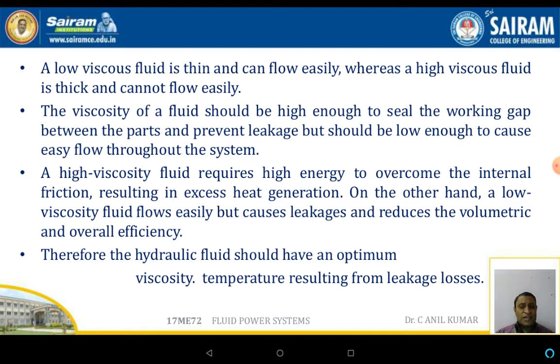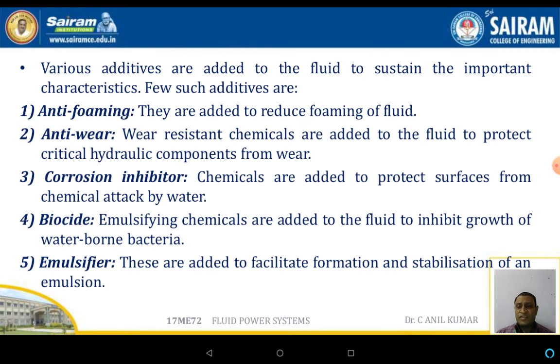On the other hand, low viscosity fluids flow easily but cause leakages and reduce the volumetric as well as the overall efficiency. Therefore, the hydraulic fluids should have an optimum viscosity and temperature to reduce leakage and losses.